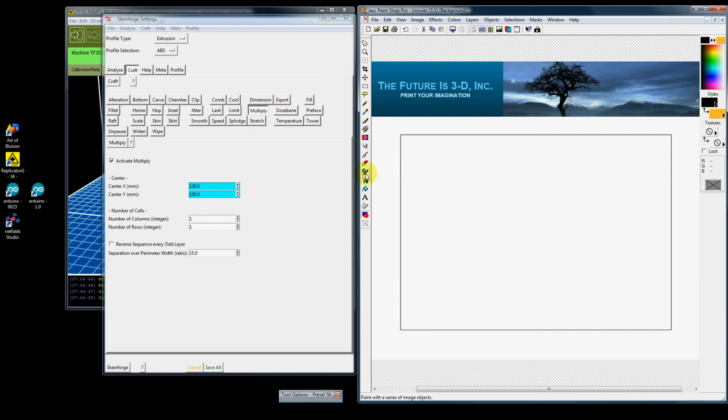So when your print job starts out, no matter where your head is at, it's going to auto home. First we auto home the Y, and this will move back, so your head will be here. Then we auto home X, and we auto home Z. So you'll be at this origin right here, 0, 0, 0. When the print job starts out, if you don't, it will start out and end up over here, and possibly end up off your plate.